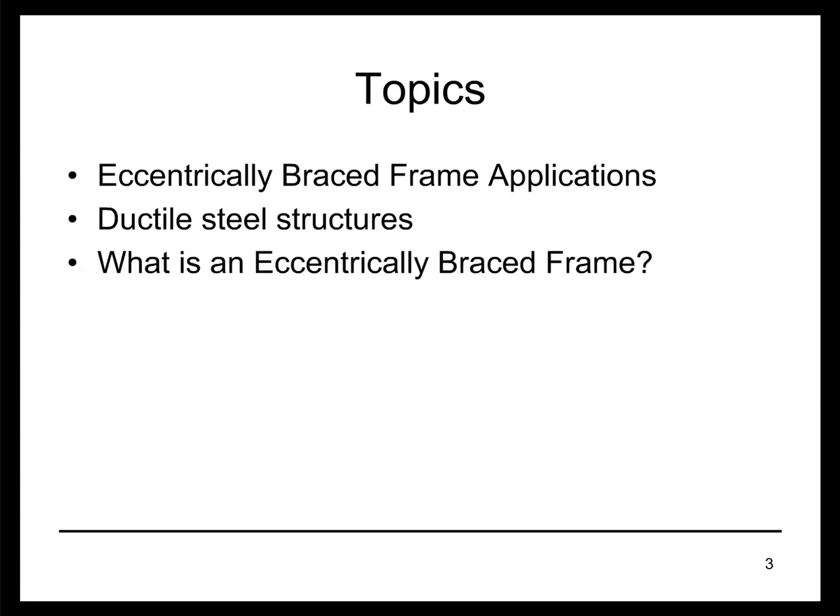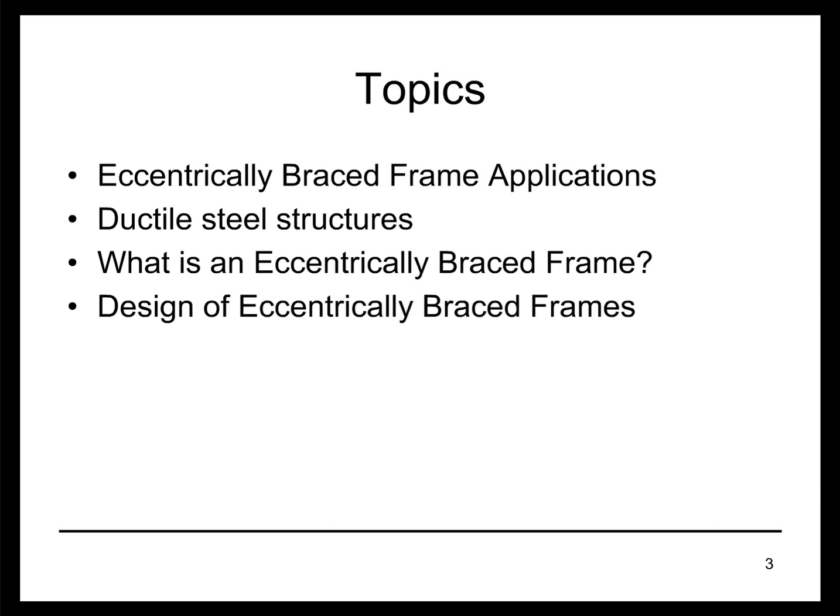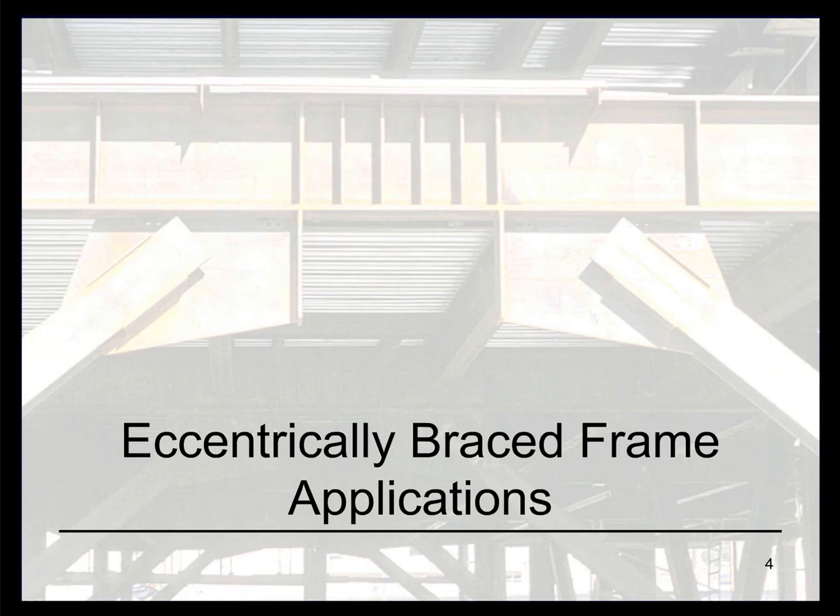So we'll talk a little bit about how and what sorts of buildings eccentrically braced frames are used. We will cover the principles of ductile design of steel structures very briefly. We'll discuss what makes an eccentrically braced frame an eccentrically braced frame, and a spoiler alert, it's the eccentricity. And then we'll go into the design requirements for eccentrically braced frames.